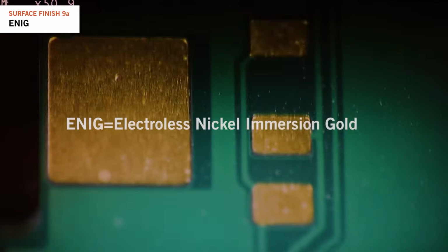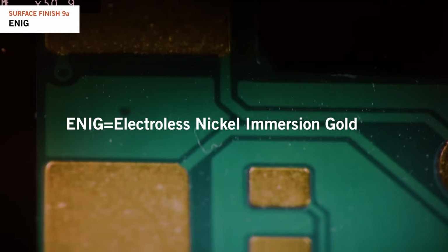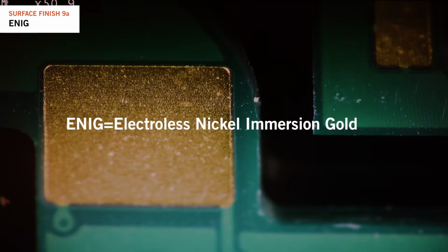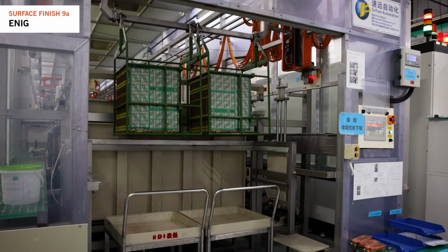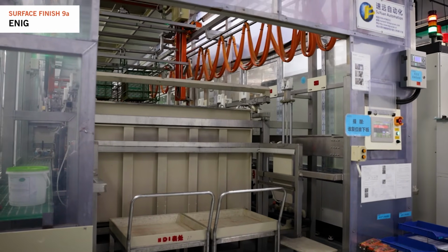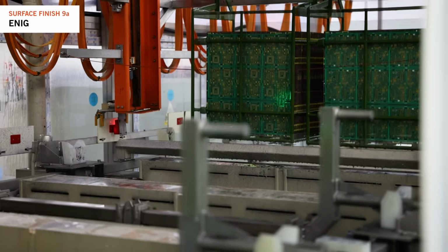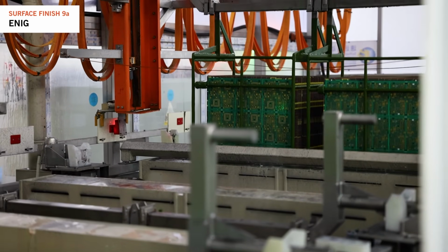ENIG stands for electroless nickel immersion gold. It's the most common surface finish for high reliability PCBs. Surface finishes are necessary to prevent copper oxidation over time and allow customers to solder components to the PCB. The ENIG process is very complex and requires careful control.